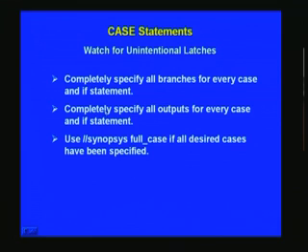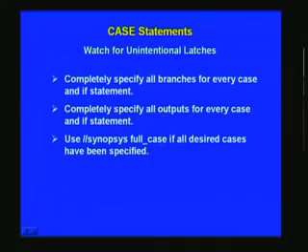Similarly, completely specify all outputs for every case and if statement. We have seen this also in an always block earlier using case, where we had 8 outputs, D0 through D7, and we took care at every case statement that we reset all other unwanted outputs other than the one which we wanted to set high. That is what it implied here, and use full case if all desired cases have been specified.